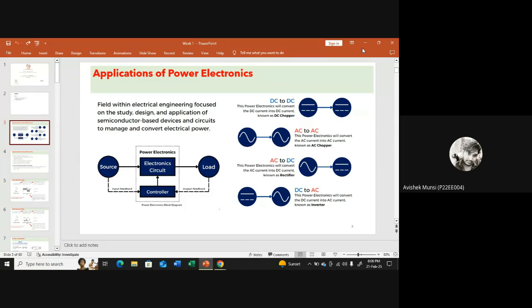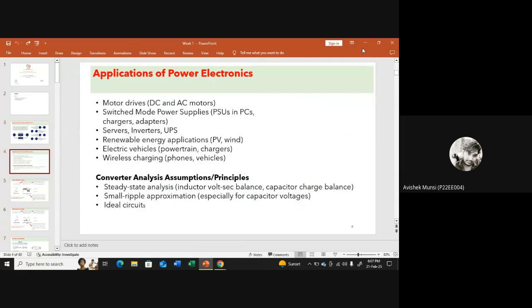So basically, what I'm saying is that in case of power electronics, we mainly deal with converters which are DC to DC converters, inverters and rectifiers. Mostly we're using those, and in advanced cases, we'll obviously use AC to AC converters. In books, we will see that AC to AC converter ends with cycloconverter. But if you are doing power electronics, if you're going to design power electronic converters, then you have to start with matrix type of converters in AC to AC. Okay, so what are the applications of power electronics?